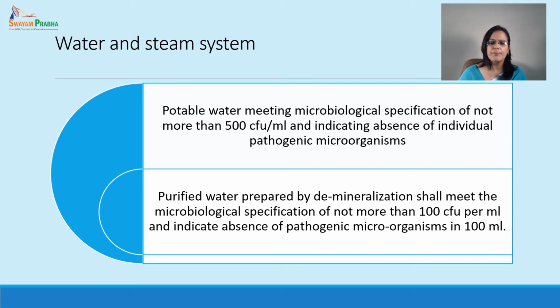Purified water prepared by demineralization shall meet the microbiological specifications of not more than 100 CFU per ml, and it indicates the absence of pathogenic microorganisms in 100 ml.